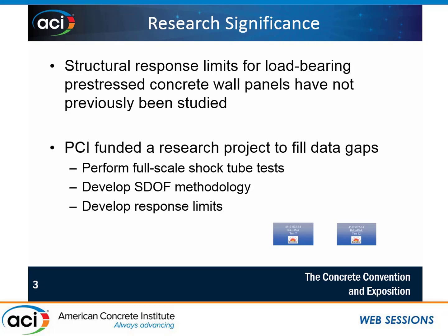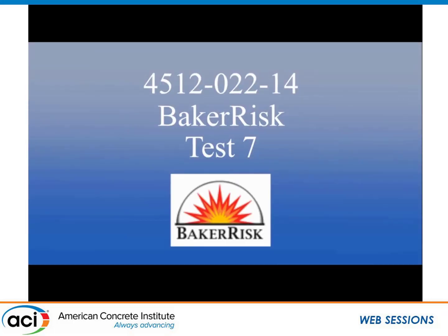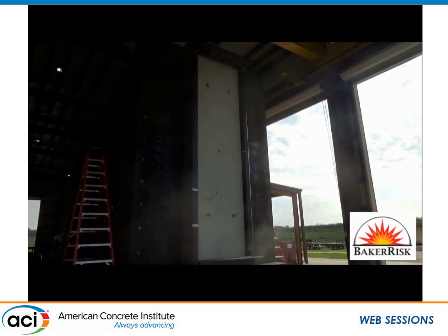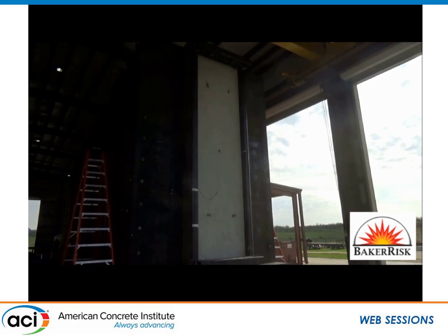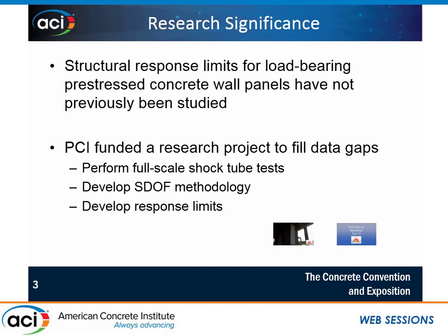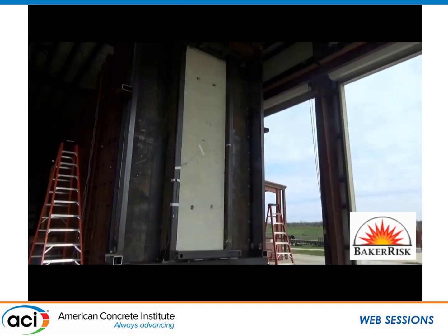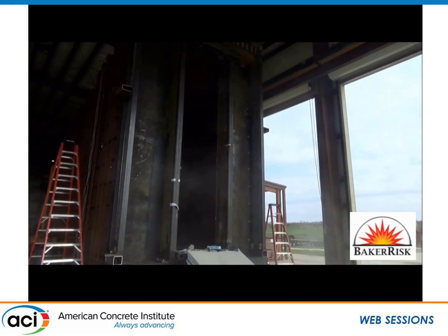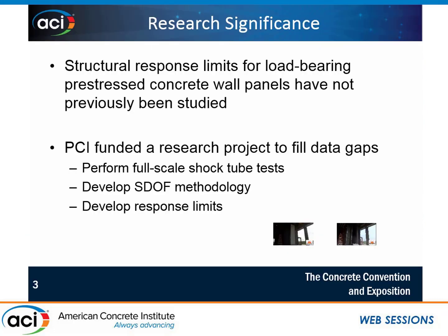If I'd known the student competition was going to be behind us, I probably would have just shown videos the entire time to drown out their noise, but there are a couple of videos here. This is a non-load bearing panel tested successfully in a shock tube, and that's good panel performance. That's what you want, and what you want to try to prevent is this happening. This is a load bearing panel that's tested, and you'll see it responds and then it fails catastrophically due to P-delta effects.